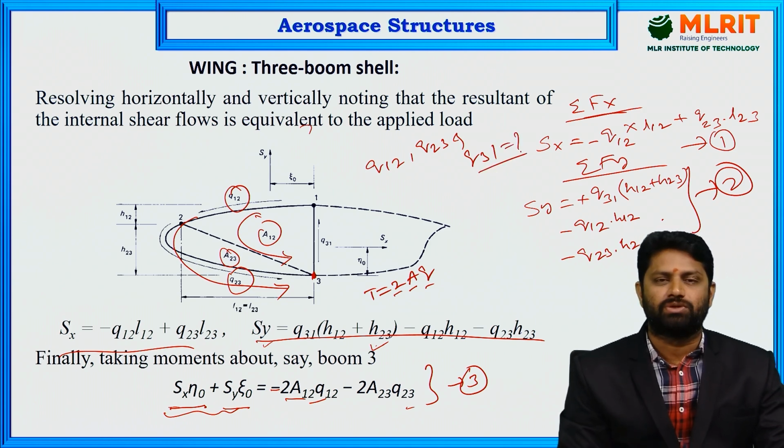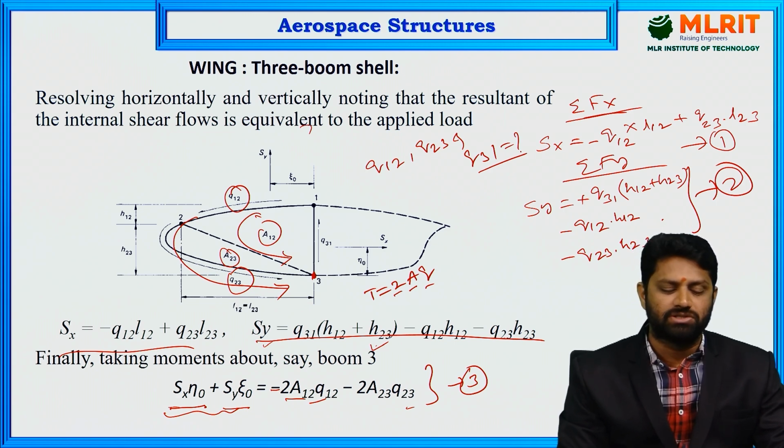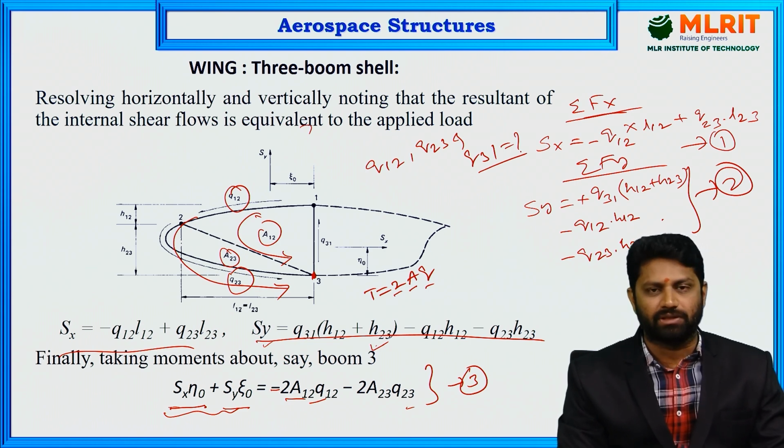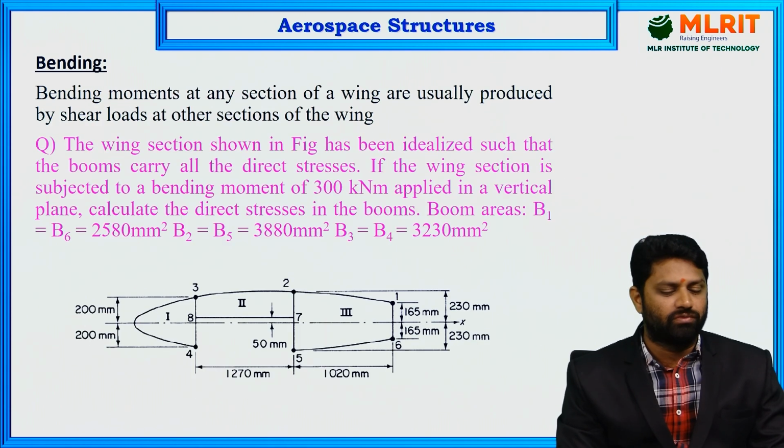Okay, so rather than finding the shear flows using different methods, it is better to use these equations of equilibrium so that we can easily predict the shear flows in the three boom wing shell. Okay, so now let's move on to the next one.